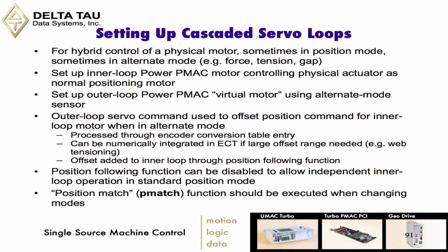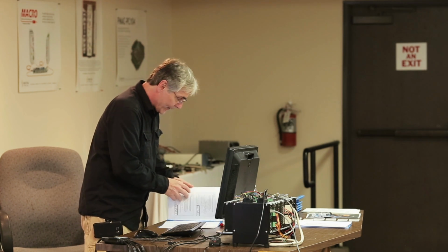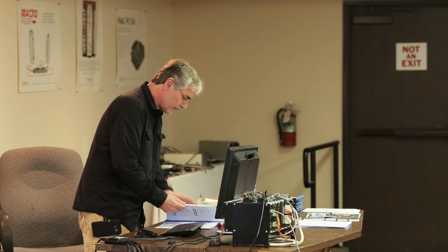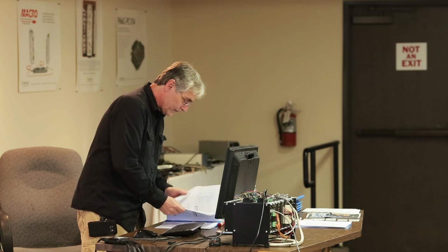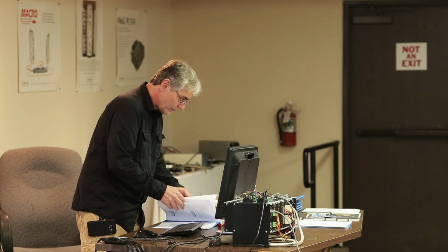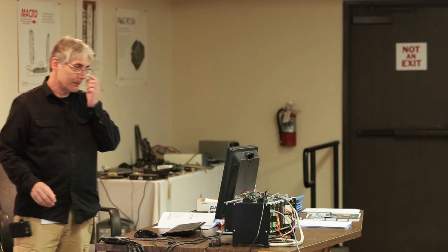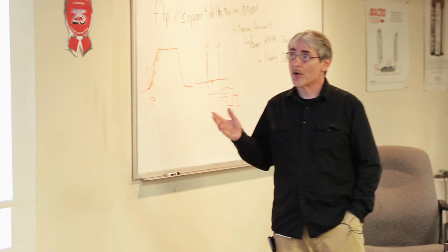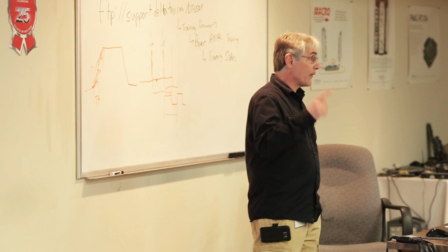Let's talk about motor commutation, and this will close out the day for us. When you have a typical three-phase motor, the drive can do the commutation on the motor, or Power PMAC can do the commutation on the motor for you. Basically what's going on in commutation is switching the direction of the current phases in the motor to maintain the amount of torque you want and the desired direction of motor rotation.